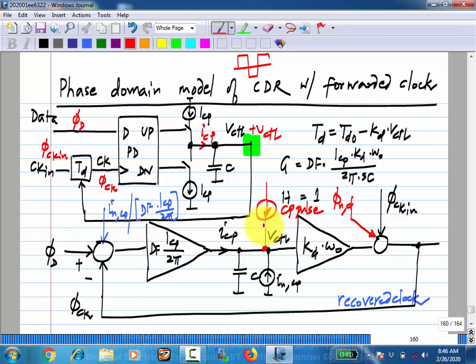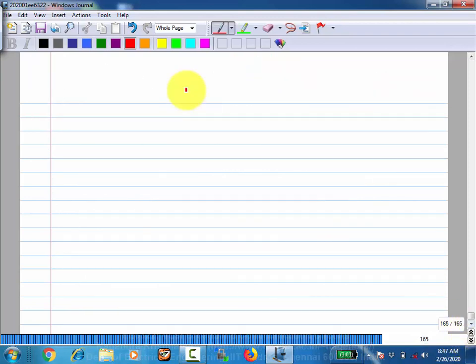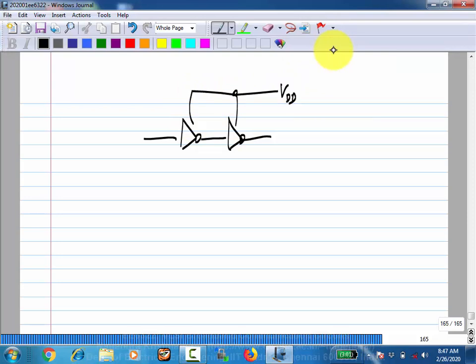You can, right? I mean, if this TD is only discretely variable, then it may also model that. On the other hand, it depends on how you make the delay line. So let's say you make an inverter chain and vary the supply. In this case, the delay will vary continuously. Of course, you cannot go below a certain value in a given process, but it does vary continuously.